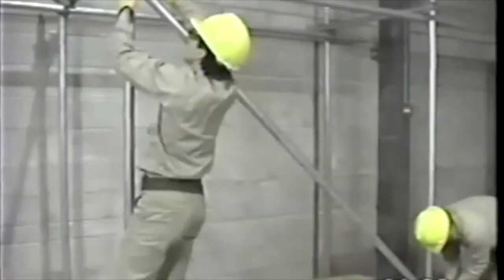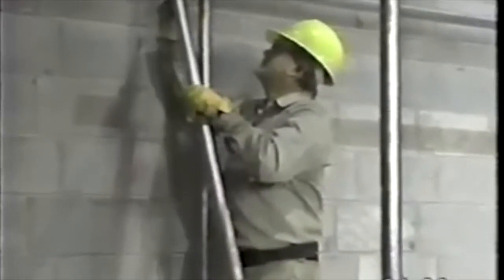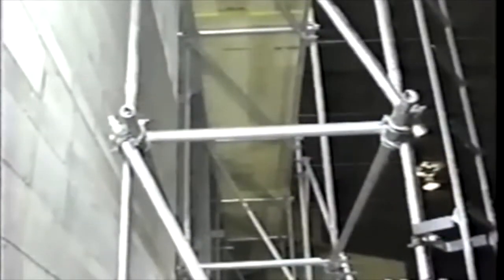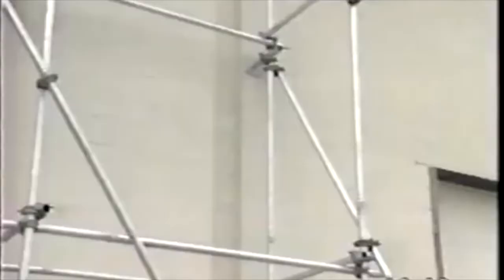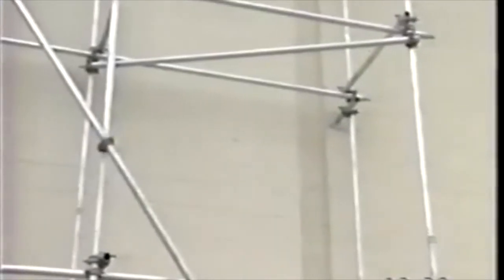Cross bracing is installed across the width of the scaffold at least every 3rd set of posts horizontally. Diagonal bracing is used and installed at approximately a 45-degree angle from near the base of the first outer post upward to the extreme top of the inner post to maintain structural integrity. For stability, the entire scaffold must be tied to and securely braced against the building or structure at intervals not to exceed 30 feet horizontally and 25 feet vertically.